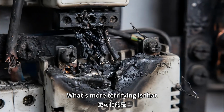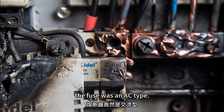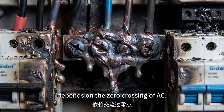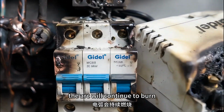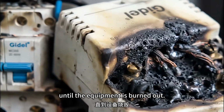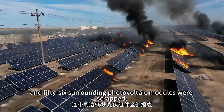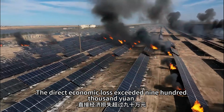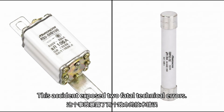What's more terrifying is that the on-site investigation found that the fuse was an AC type. The arc quenching principle of AC fuses depends on the zero crossing of AC. Used in a DC circuit, the arc will continue to burn until the equipment is burned out. Eventually, the combiner box burned into an iron shell, and 56 surrounding photovoltaic modules were scrapped. The direct economic loss exceeded 900,000 yuan. This accident exposed fatal technical errors.